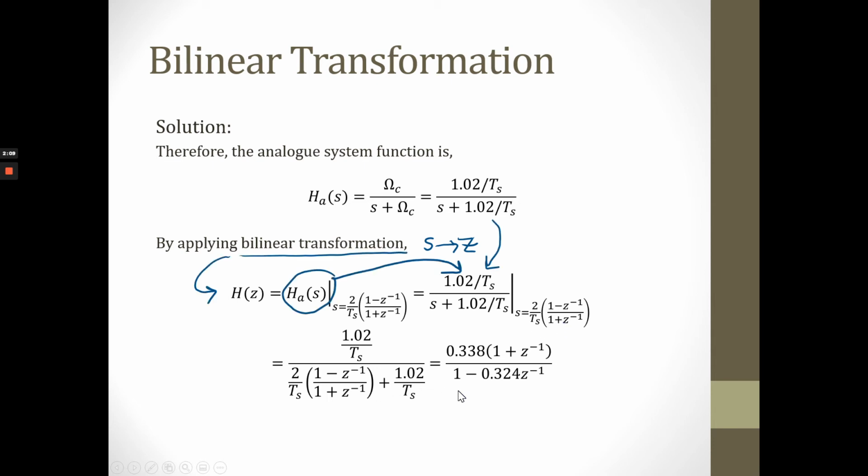So the next one, after we substitute this equation into this equation of the frequency response in S domain, we have this equation. And after we simplify and rearrange this equation into one equation in the numerator and one equation in the denominator, we have this function of the frequency response in Z domain.